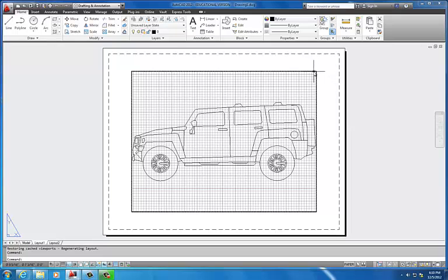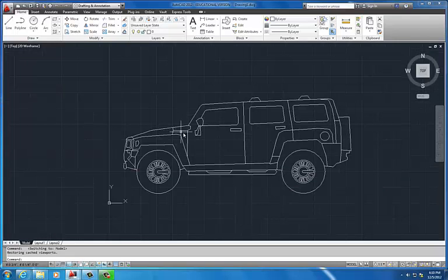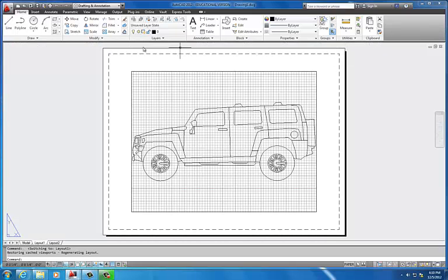And then this is what we call a viewport. This is kind of like what I call a window into your model space. So again, this is paper space. This is model space. In model space, we can draw the world, theoretically. In paper space, we can just fit what will fit on, in this case, an 8.5 by 11 piece of paper. Sometimes we'll use bigger paper to plot bigger stuff, but in this case, this is what you're going to use, the standard letter size sheet.